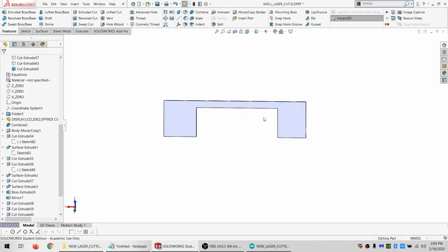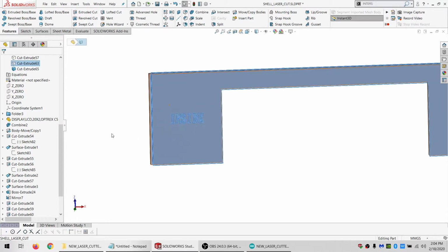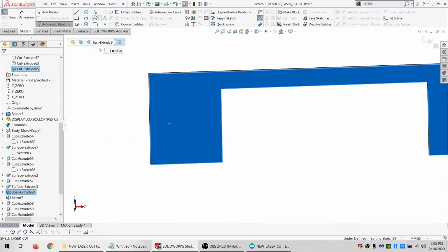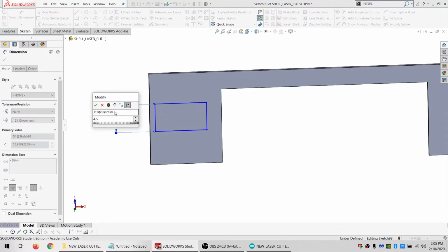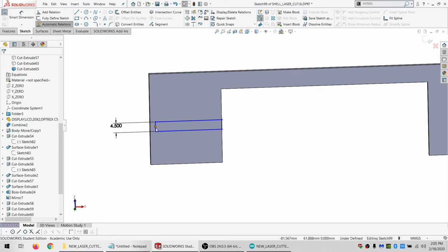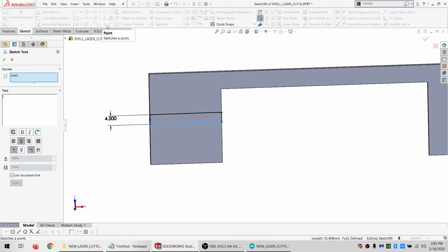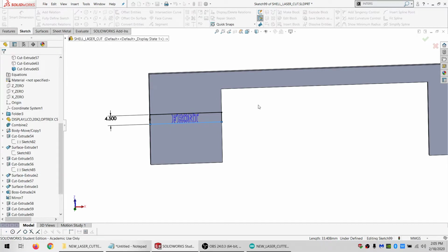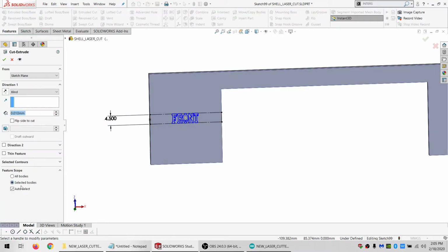And I want it on the back, the same as that. This is 4.5. This is coincident. And I can save myself a line by making this midpoint. And there we go. And then there we go. Make that for construction. Extrude cut. Only applying to that.